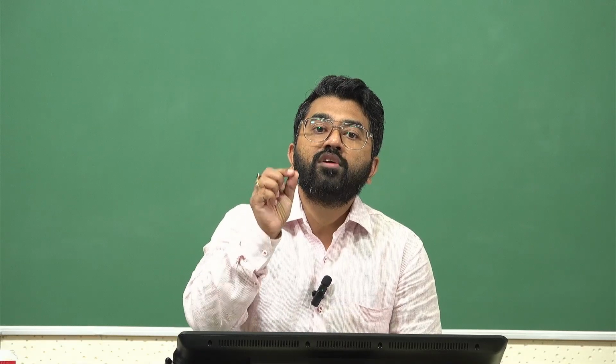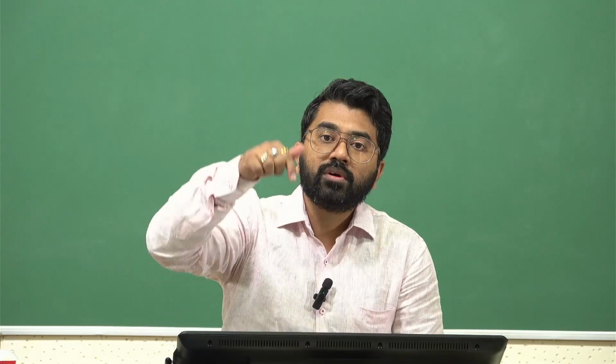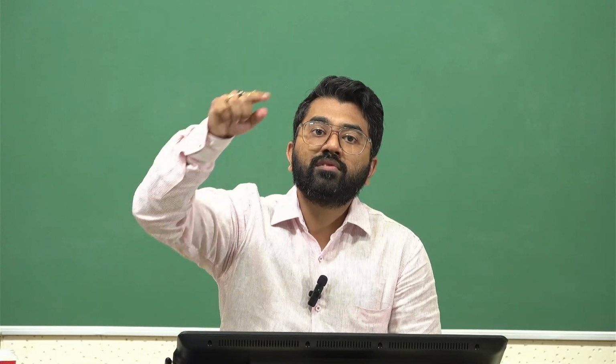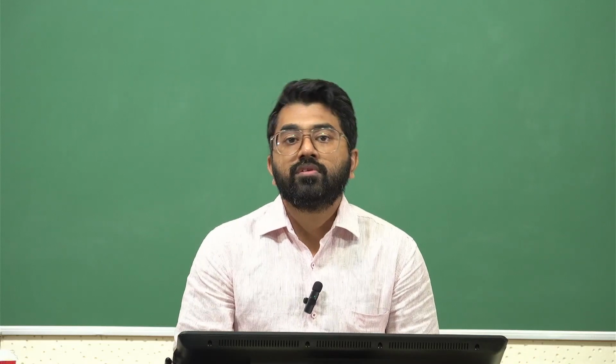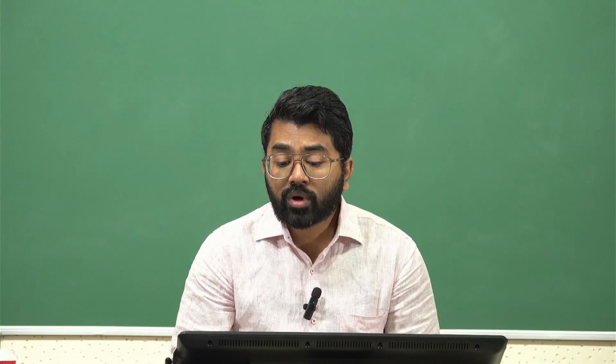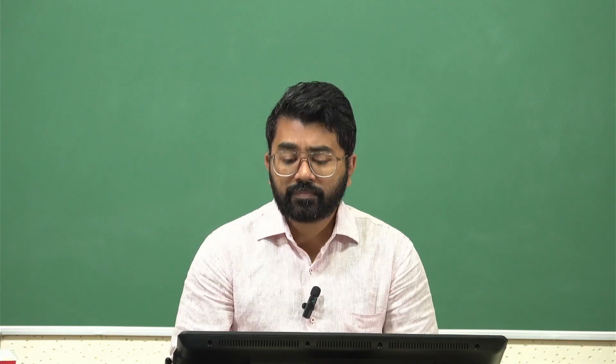So if you change the head of the indenter, it may give a very different solution, right? Because that's how it is poking on the skin. If it is a flat surface versus a curved surface, it has a very different kind of load response, right? So as this is done, a 3D scanner scans the coordinate which is connected with this indenter. So it's a very high precision measurement, which takes displacements in the order of less than a millimeter, right? And you're measuring forces much less than a Newton.